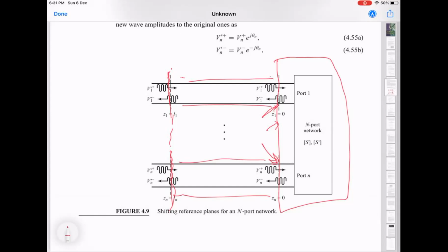but you could see a very different phase response if one doesn't account for that. So if the situation is an extremely simple case of an ideal 50 ohm transmission line, which means completely lossless, exactly 50 ohms, no reflections, nothing, then it's trivial. It can be fixed by a simple calculation, just this phase accounting. You just add a negative phase, and that's what this electrical delay setting, which is provided in these instruments, allows you to do. One can always try that first to see if it makes sense. It just resets the additional phase and then plots the thing.